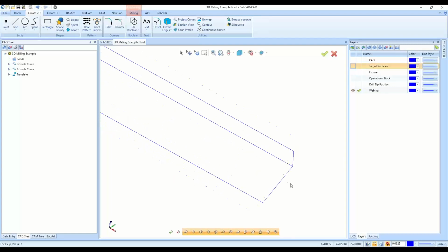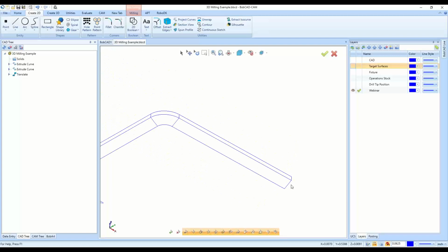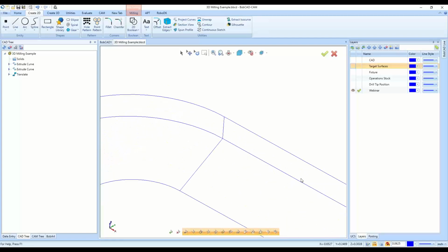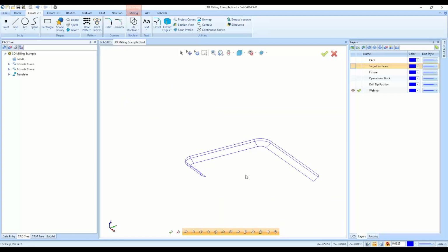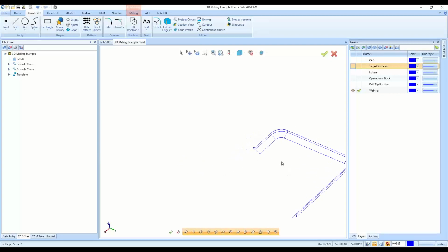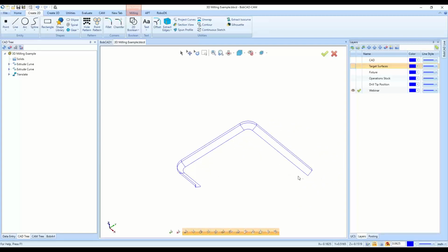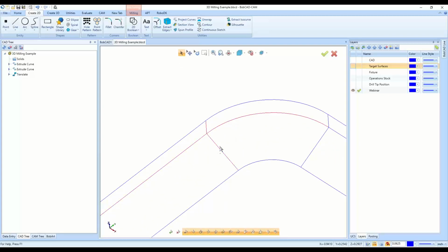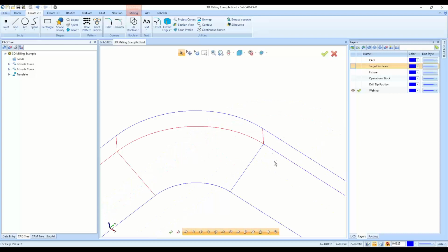And now it picks up all of the edges of the surfaces that I've selected. Picks up on the inside here too. You don't necessarily need that for a boundary, and it's also kind of in the way if I want to chain select, which is what we're going to be going over next. So interfering with chain selection can be quite bothersome. So I can window select each of these entities.